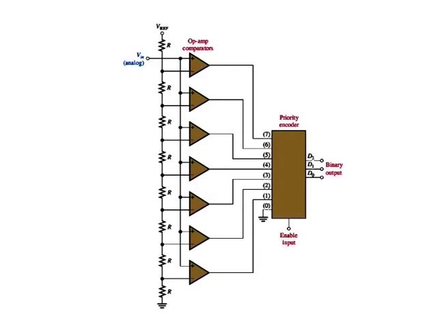The simultaneous or flash method of A to D conversion uses parallel comparators to compare the linear input signal with various reference voltages developed by a voltage divider. When the input voltage exceeds the reference voltage for a given comparator, a high level is produced on that comparator's output. The figure here shows an analog to digital converter that produces 3 digital binary numbers on its output, which represents the values of the analog input voltage as it changes.